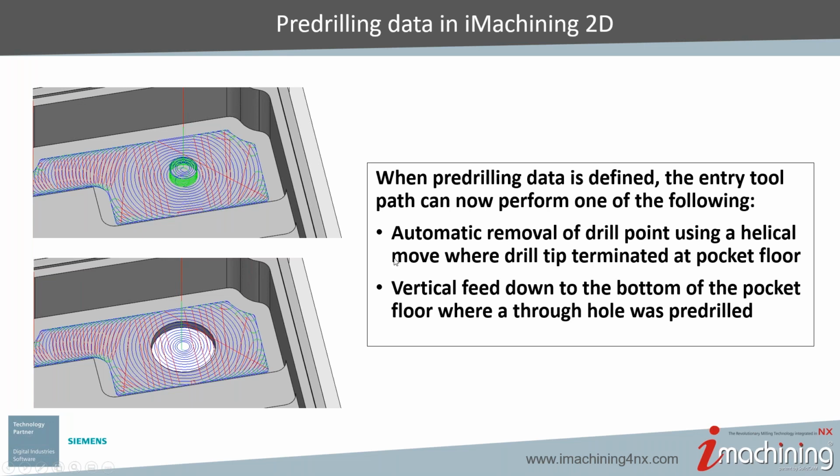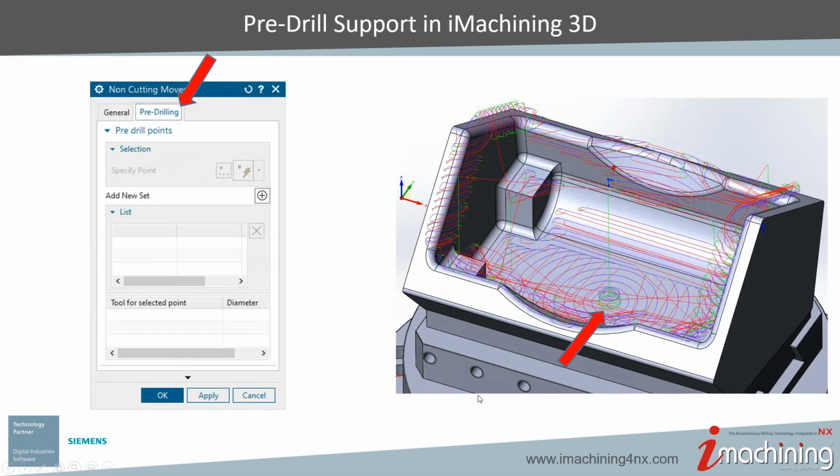Even if you're just throwing in a 1/8 diameter drill or whatever drill is in the part, I always say this: if there's a drill in the tool carousel for the part you're machining, pre-drill your pocket just so there's some hole in the center. The difference between just having a 1/8 hole for where it plunges really makes a huge difference on the helical end mill when you're plunging.